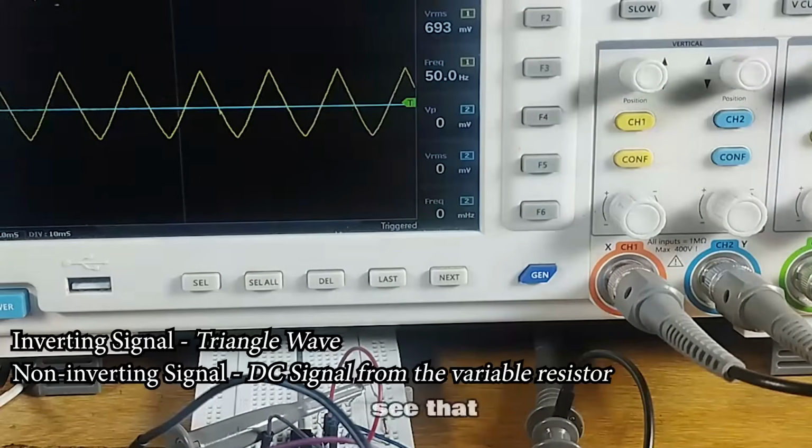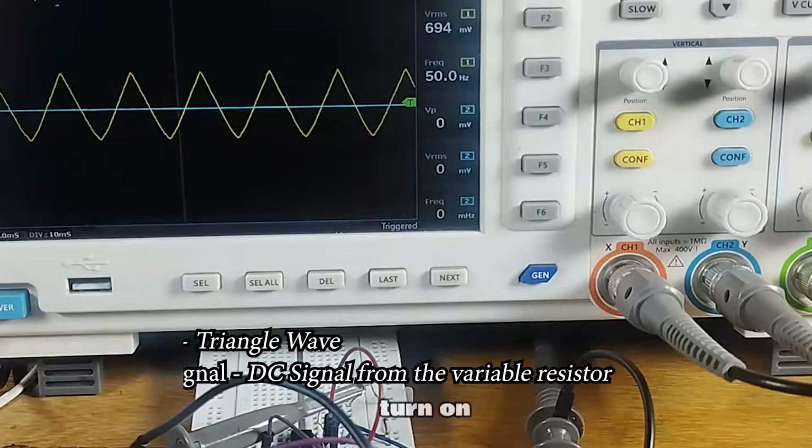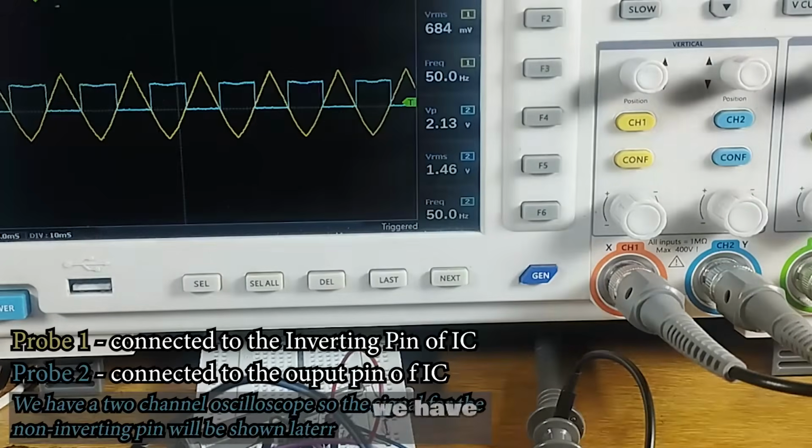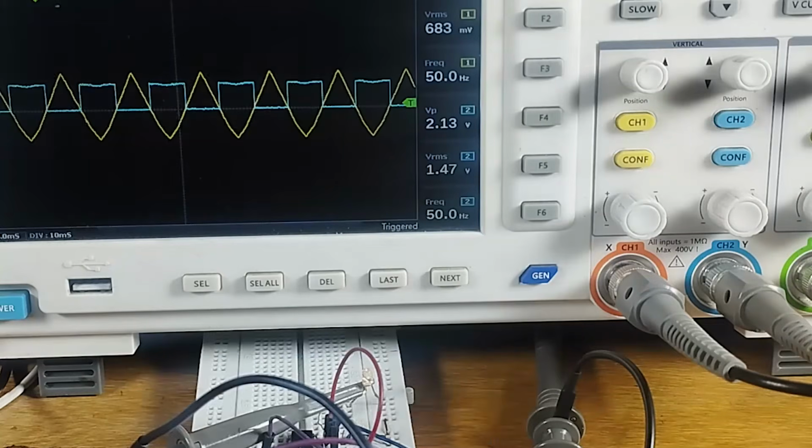We'll see that if we turn on our power supply, we see what the output is like. We have a square wave, of course, because remember we have the non-inverting signal to be a steady signal. We're going to change its level with the variable resistor's wiper.